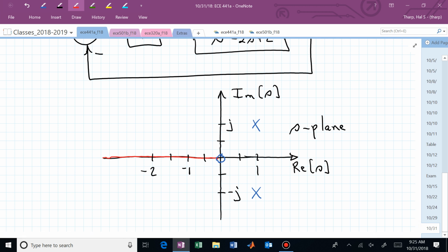But isn't that the part of our root locus? What's our pole zero excess? I'm asking why, so that we can figure out asymptotically what happens to the root locus. Our pole zero excess is 2 minus 1. It's 1. So what's our asymptote angle?